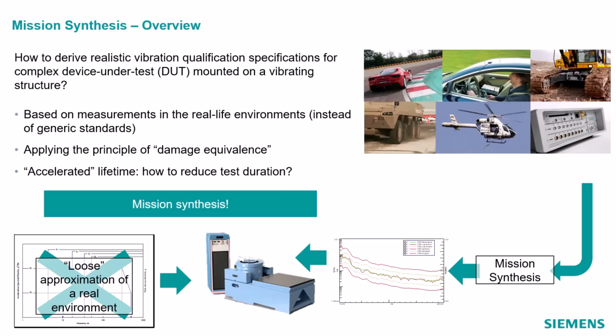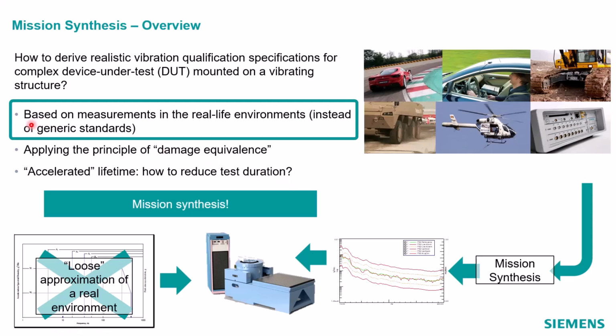With the mission synthesis approach, we want to base that PSD profile on measurements taken in the real-life service environment of that component rather than using a generic standard. The idea being that these generic standards don't cover exactly what that part or that component is going to experience in the real world. So let's base this test on the actual vibration environments that that part or component is going to experience in the real world.